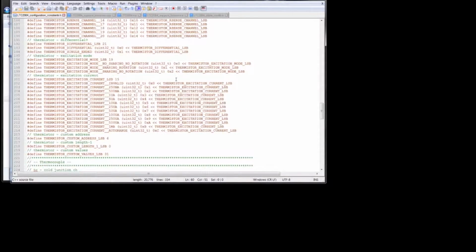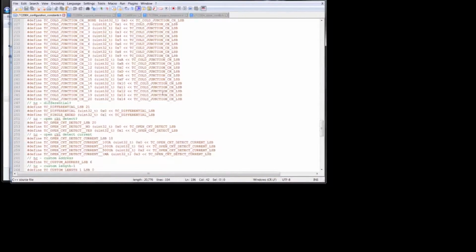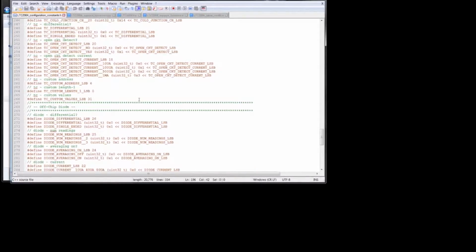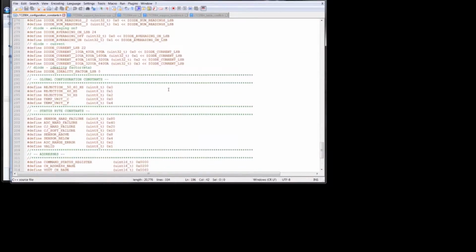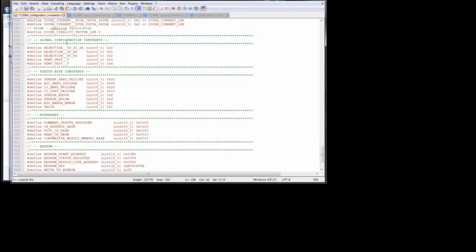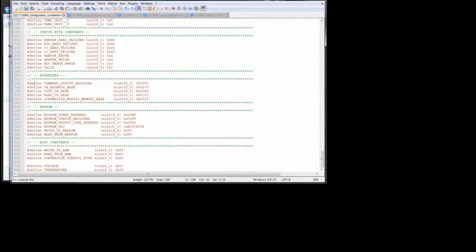It won't work during runtime, right? If someone in the barbecue controller changes a thermocouple type in the GUI, I can't go recompile it, right? So this isn't going to work, but it works if you're going to have a static configuration, or if you can compile and upload different versions of code, this works pretty good.